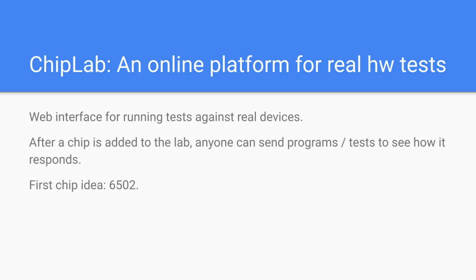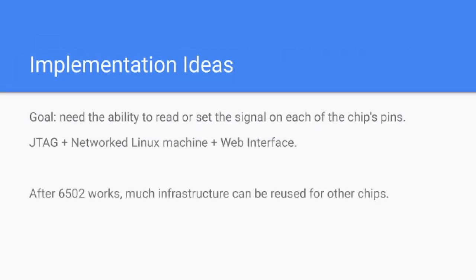Modern 6502 vendors actually provide an implementation of the chip in a hardware description language. This sort of represents the same logic that they would use to actually have the chip produced. This gives us an easy-to-use reference when tracking down any issues. And finally, 3, it is a fairly simple 8-bit chip running at a modest speed. This means that certain electronic issues, like signal integrity, should not be much of a problem.